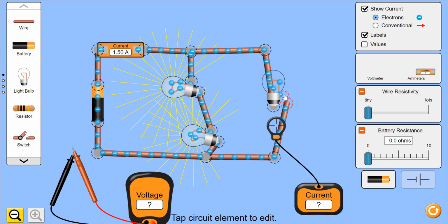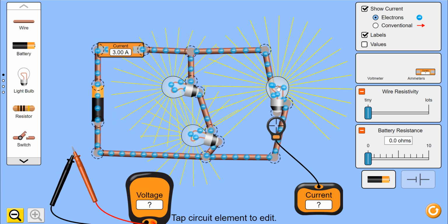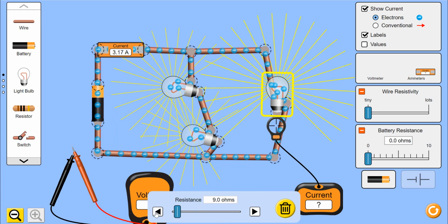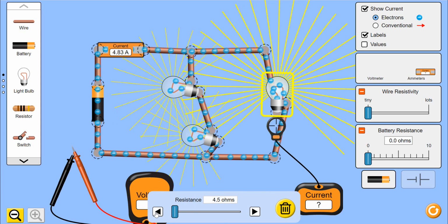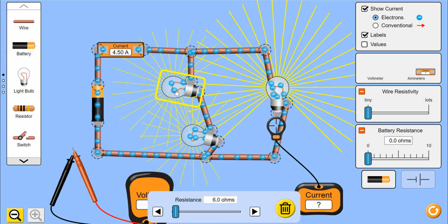What if I burn out the other side? So there's my light bulb. Let's hook it back down to 5 ohm. That's what we had. And then let's delete one of these other light bulbs. Let's say that filament burns out. Once one of the filaments burns out, that path is no longer available. If this bulb burns out, it's actually going to cut off both of these light bulbs. So I'm going to delete that there. Let's track this total current again, which is 4.5.